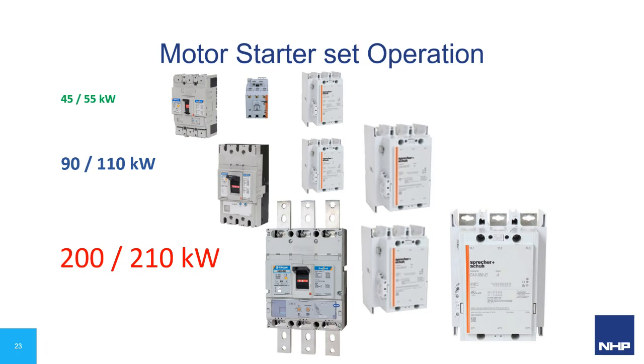The replacement was a requirement of the standard. However, when we consider the ratings of the contactor to correctly size it based on pre-MEPS figures, it makes good sense to do the same to the contactor these days, to avoid possible catastrophic failure or unexpected breakdowns during production cycles, not just based on whether Type 2 coordination is required or not. Because we're subjecting the smaller contactor to the same or more forces, it's probably not a bad idea to increase its size, to increase its reliability and its duty factors.